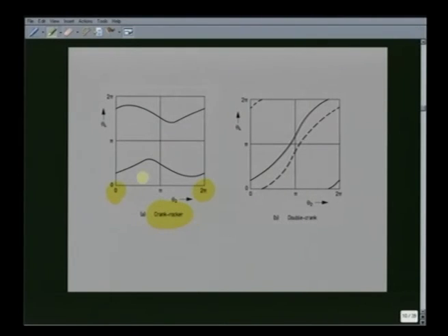And theta 4, because theta 4 is the rocker angle, only goes from a minimum value to a maximum value. And there are two branches, one is here and the other is there. Because it is a rocker, again it rocks either from this minimum value to that maximum value or from this minimum value to that maximum value. As we said earlier, a Grashofian crank rocker has two distinct branches, two distinct modes of assembly, that is why these two curves never cross each other.